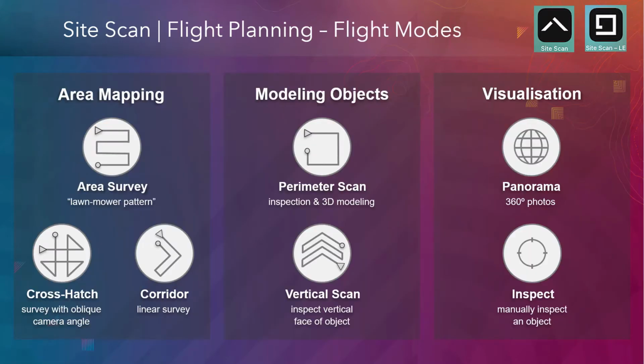When planning, there are 3 principal flight modes that you would look at. Mapping for ArcGIS ready products. There's the traditional area scan, for aerial photography, digital elevation models and digital surface models, point cloud and contours, and you do it with a vertical gimbal with an 80% forward overlap and a 70% side lap. Most of your GIS ready products will come in this flight pattern.